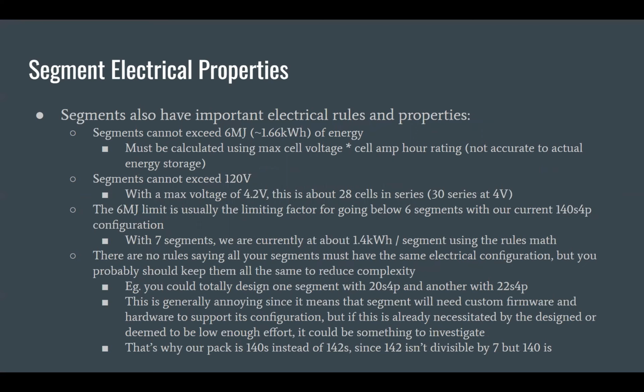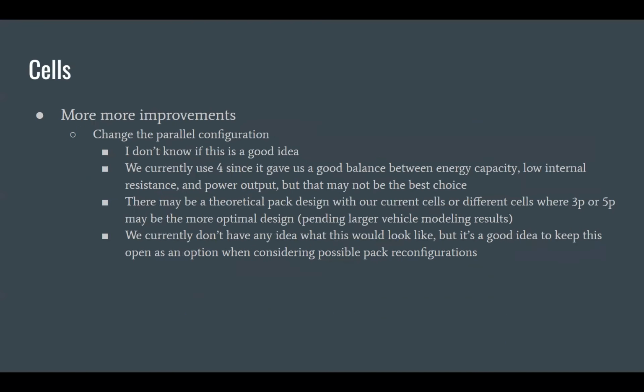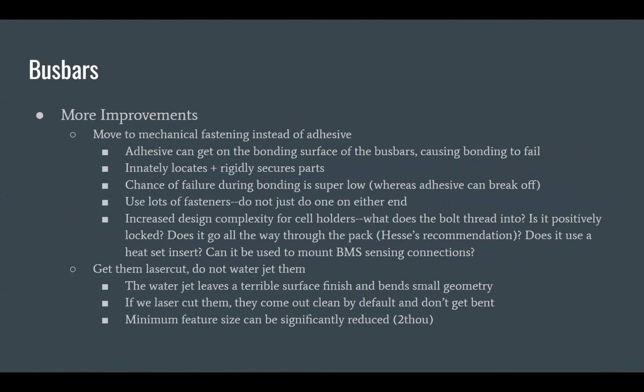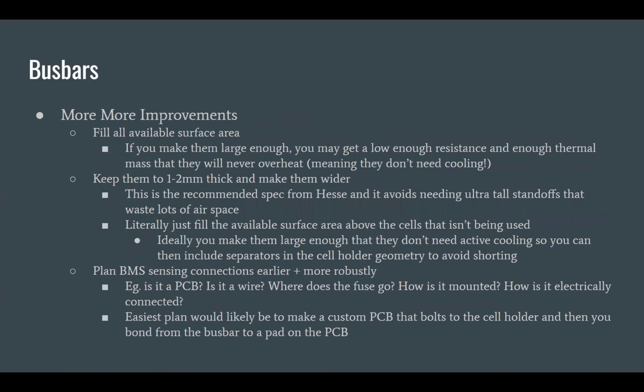Anyway, so jumping all the way back. Yeah, so jumping back and quickly finishing up our bus bars before we wrap up for today, like I mentioned, you want to basically make your bus bars as big as possible. If you can come to a design that demonstrates that the bus bar at a given size is large enough that it will never overheat and doesn't have to worry about thermal problems, then that's great.